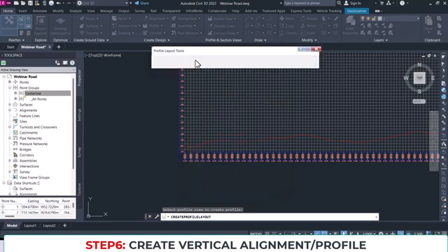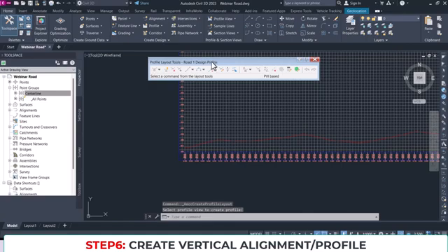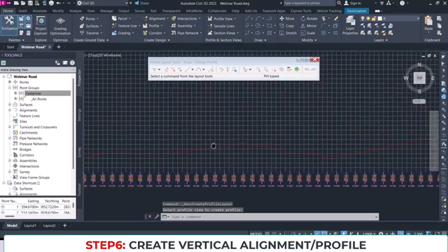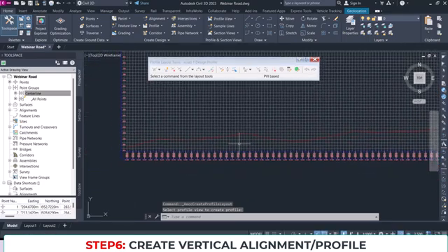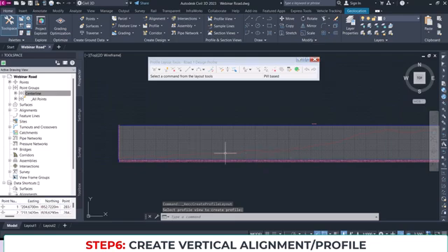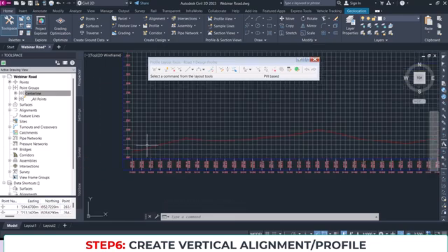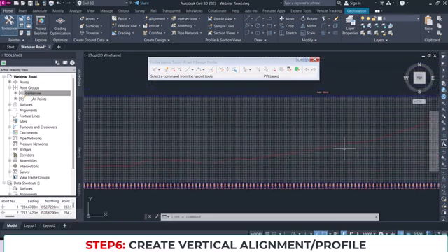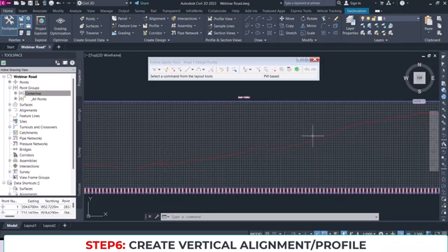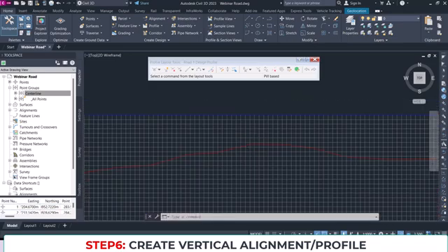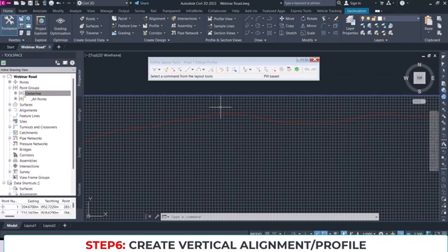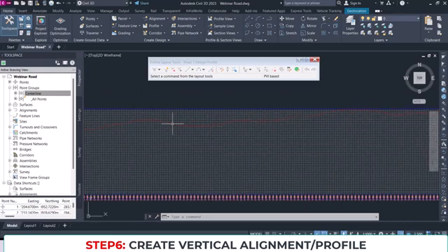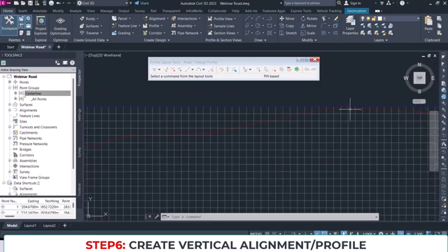So it opens up that ribbon, just like the alignment. You can create it with straight. You find a place that is relatively straight, and then draw a straight line. Now if I were to design this road, of course you have to study the profile first. After studying this profile, I find out that I can just go straight from here all the way to here, and then have a curve that will take me to this hill, and then I reach this crest here, and then I have a high point, PI here, and then maybe go down a little, or just still keep going high.